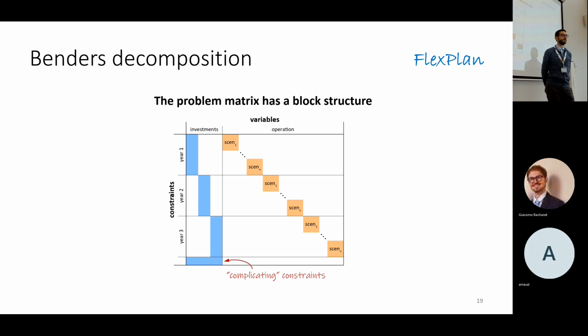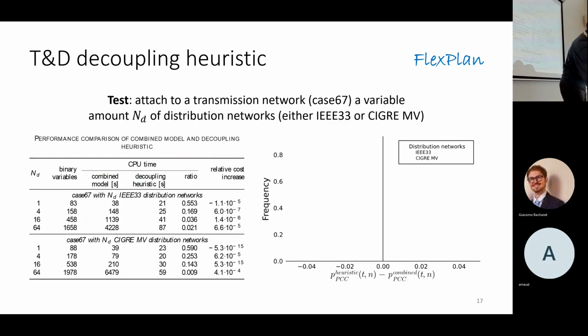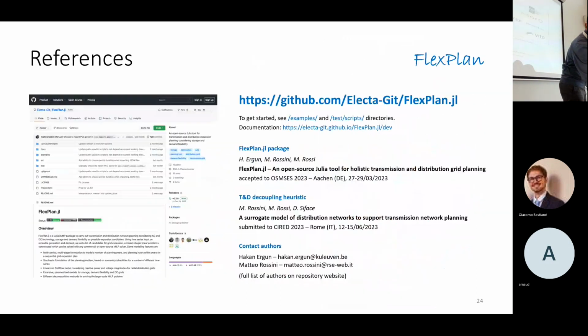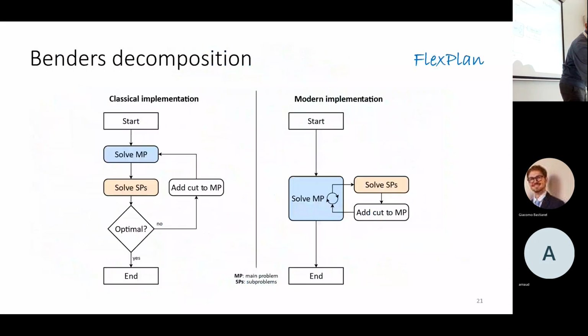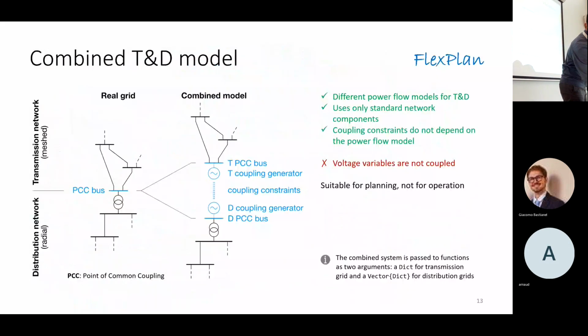So if I assume correctly, before you solve this optimization problem, you have scenario generation, which generates all the scenarios and the weights. And then you select all the candidates, the list of candidates, that okay, I will build a line here, put a storage here, and based on that, you calculate the capex and opex, and that's why you have a single stage optimization problem.